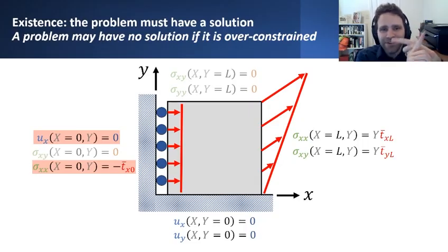And as long as those two things are mutually orthogonal directions, that I'm prescribing differing components of displacement and traction in, then I have no conflict. Prescribing displacement this way has nothing to do with how I choose to prescribe either displacement or traction in the y direction.